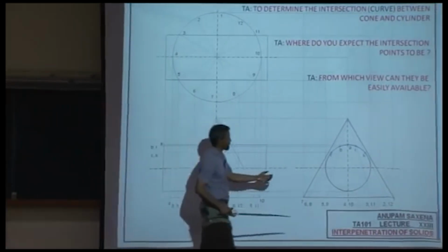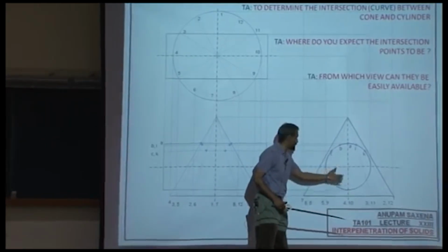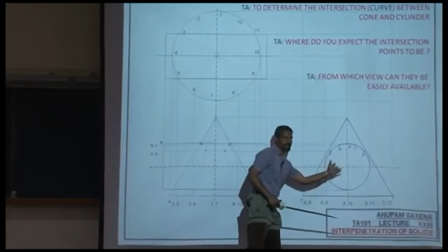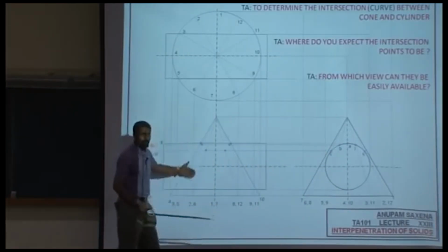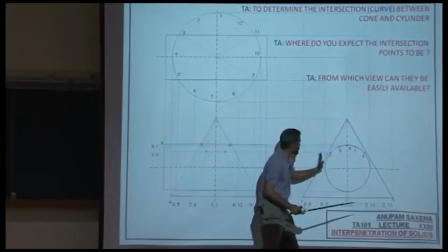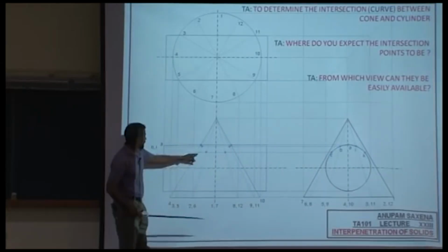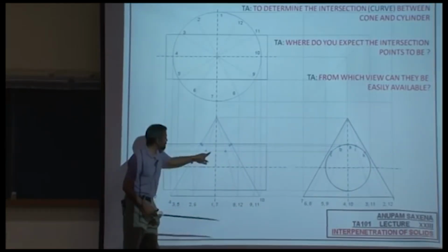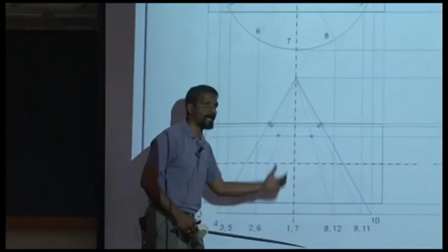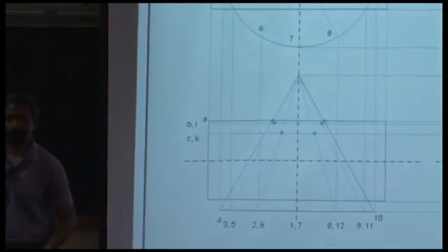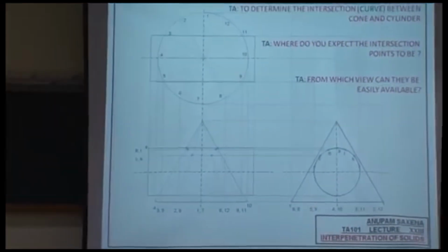Now, in the third angle projection, this is the profile view, right? If you turn it by 90 degrees this way, this part is going to be facing you here, and this part is going to be behind you. So understand that. These two intersection points are facing you, and correspondingly the other two intersection points are behind the cone. Understand that. The rest is a little mechanical.